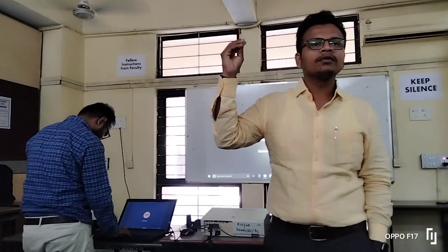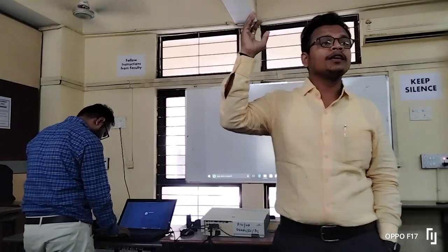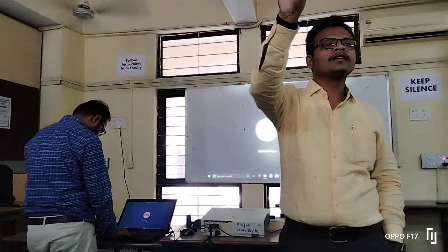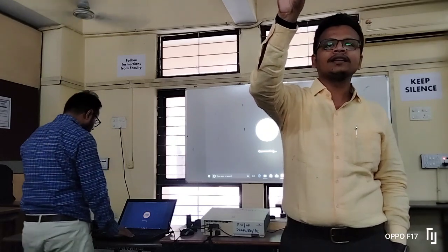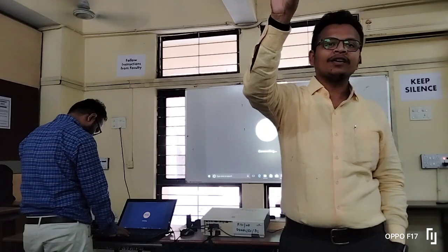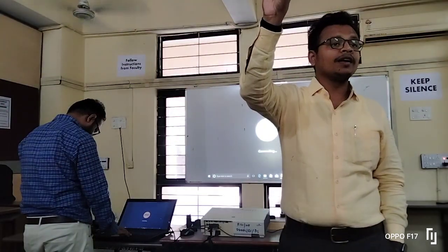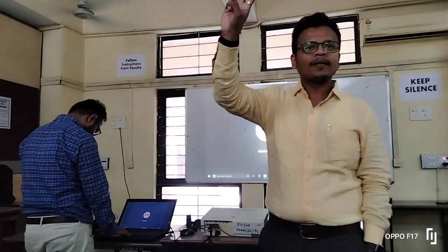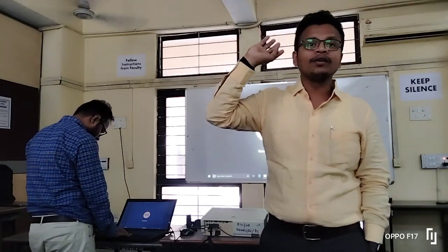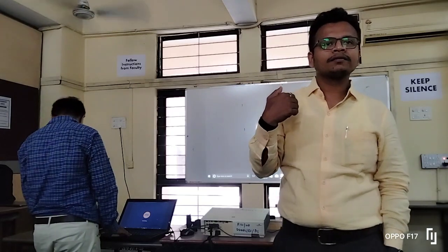Digital. અને આમાં મેં તમને explain શું કર્યું? I have explained you the use of address line, data line, and one more thing, control line. Control line is used for what? Either for writing your data or reading your data. Because with memory you can do that two things only, nothing else. Either you can read the data or you can write the data.